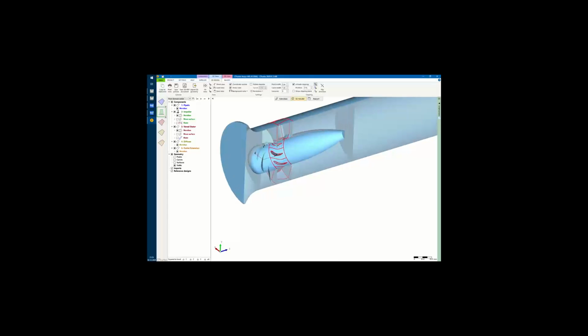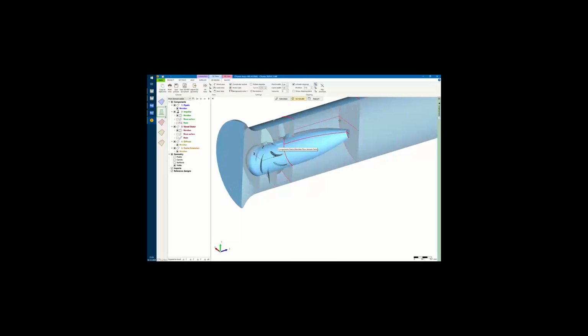What you currently see would be the volume where the fluid is transported through, and these are exported in the STEP file format. We apply some script logic to modify the STEP files or to convert them into SpaceClaim file documents and apply the named selections. And then the input into the Ansys meshing system is a SpaceClaim file format.